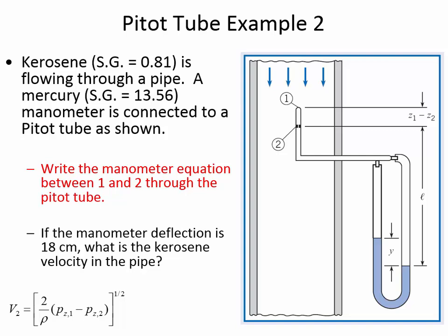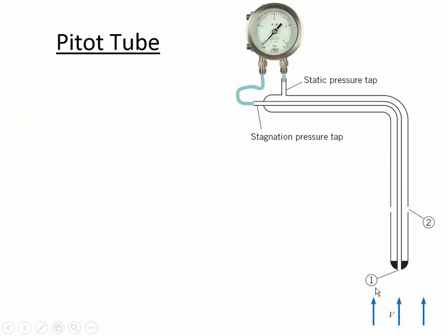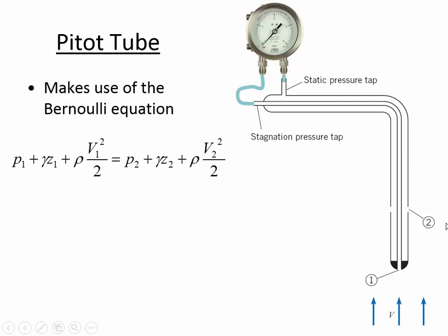It's not static. If we did this, basically what we'd be saying is we're going outside of the pitot tube from 1 to 2. If we look back at here, the way that we're getting from 1 to 2, basically, just in conception, is we're starting at 1, they're not connected, not directly. So to get to 2, we have to go through here, through the gauge, and then back through this direction. When we apply the hydrostatic equation, we can't go through the moving fluid, so we can't go on the outside of the tube, because then that's not static conditions.